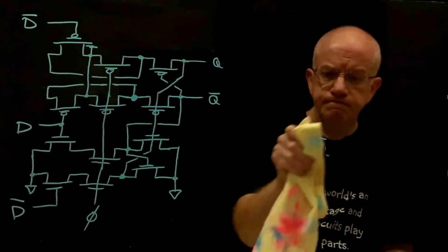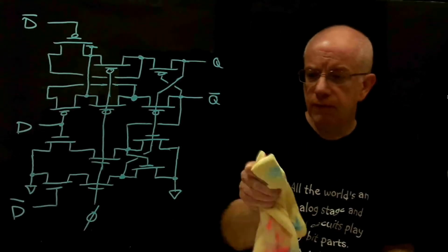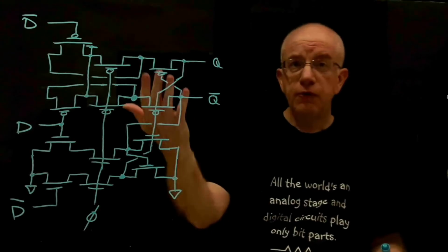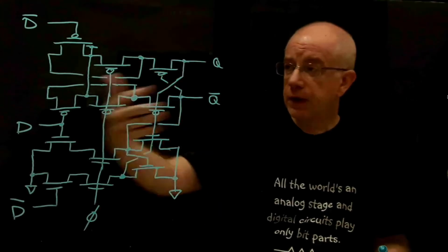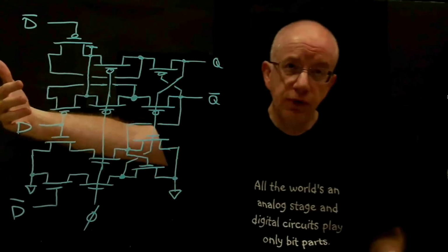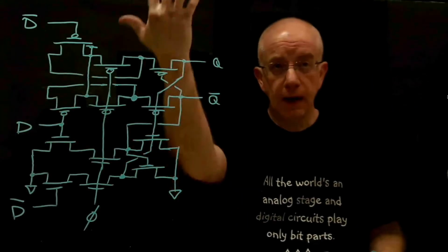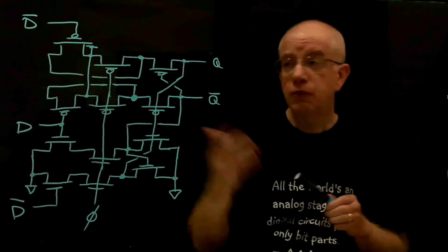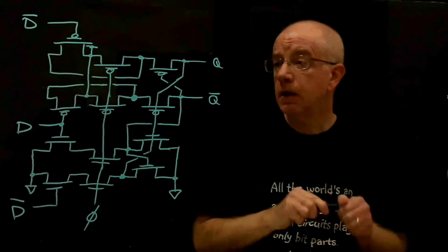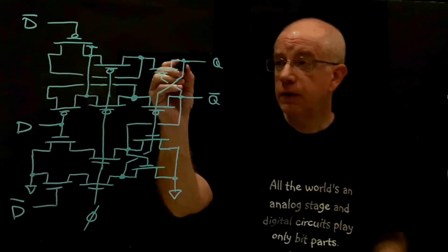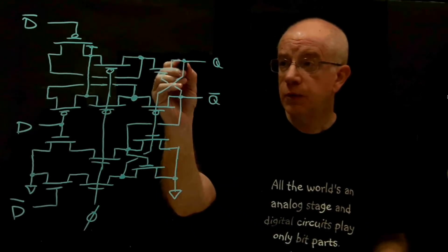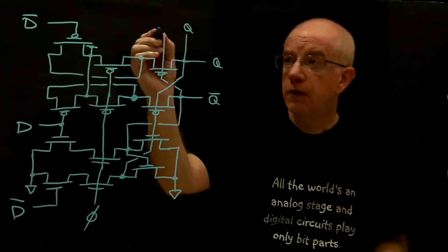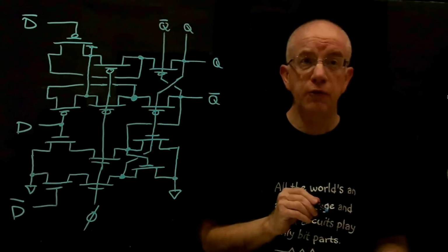Notice also, if we wanted to have something like the Q outputs available up above, like if we're having a shift register where we can shift bits in this way, but we want to have parallel outputs so that Q and Q bar are available to read out that way, that's pretty trivial because we have Q here. So we could run Q up this way, and Q bar is available here. Okay, so that's actually pretty nice.